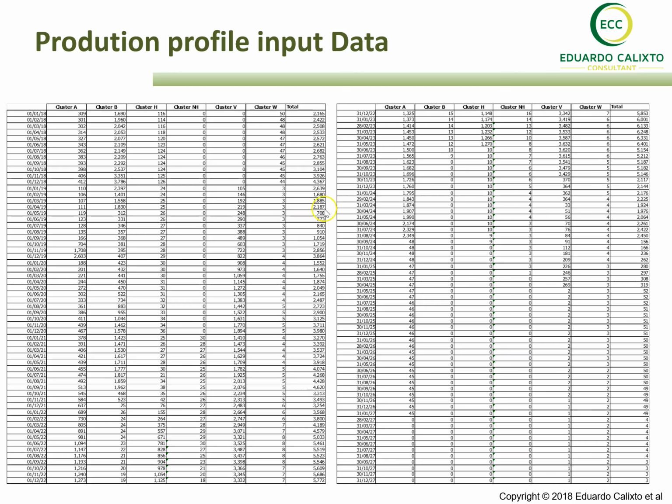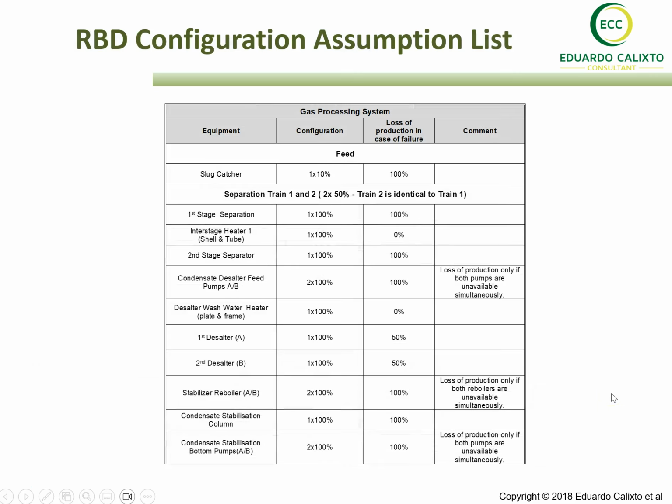And what is very interesting here is to understand that it starts with a high value, but at some point in the future, this gas production reduces. That means if I design a platform with a high level of redundant configuration, in the end I will not use the capacity. I will use maybe half of the capacity. So I need to take into account this factor.